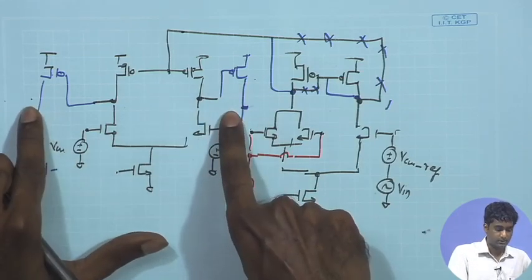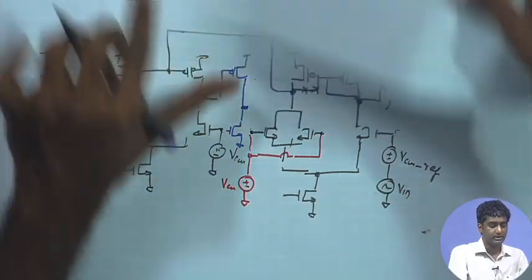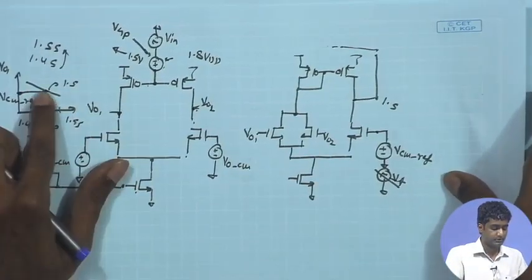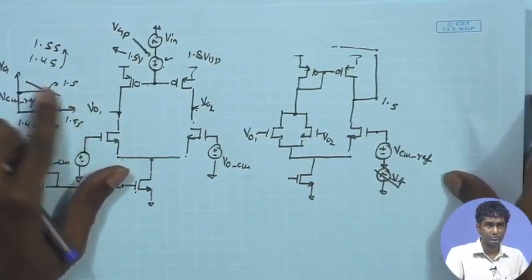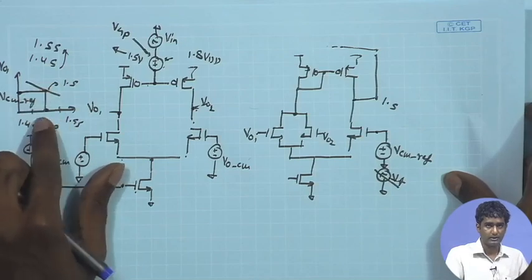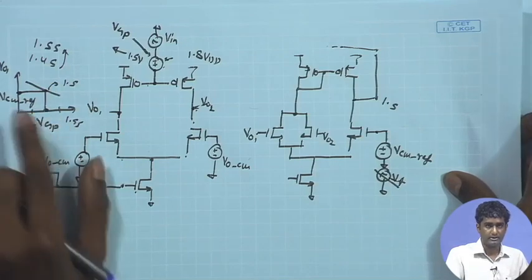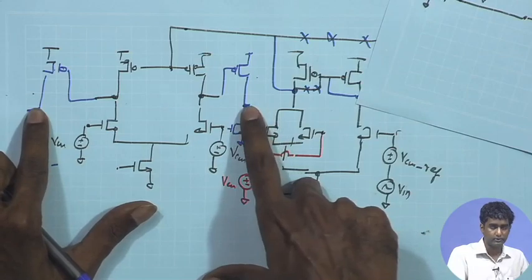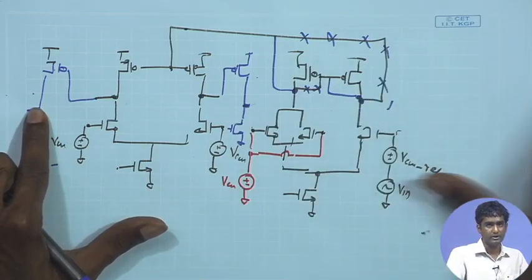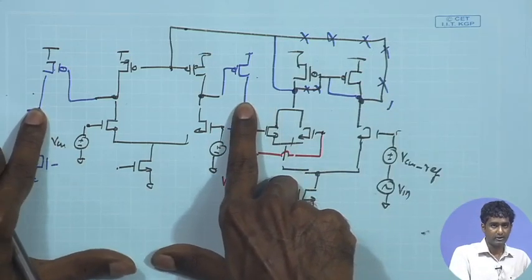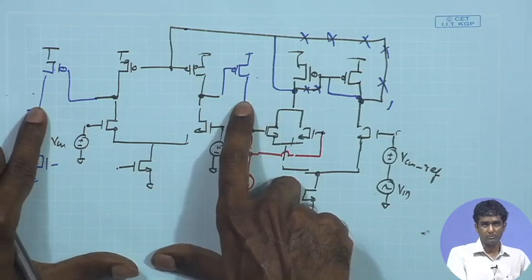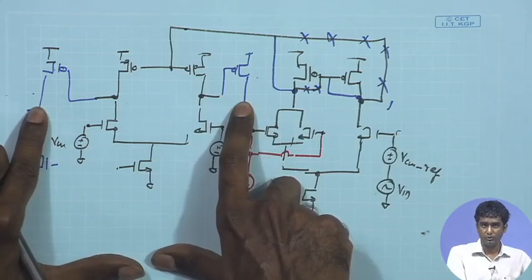Therefore the sweeping scheme that I discussed becomes all the more important, because you need to precisely locate which point you want to have at the biasing DC bias, so that the output DC levels over here obtained for the open loop operation are very close to the common mode voltage that was obtained using closed loop.